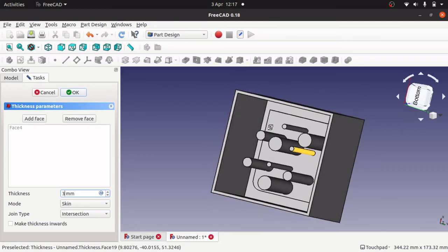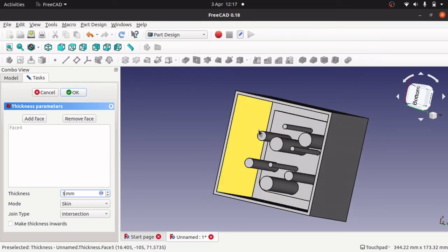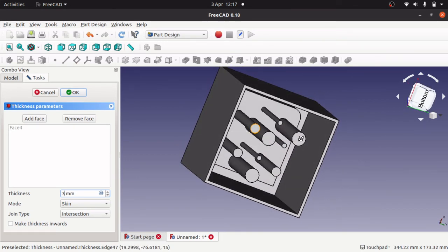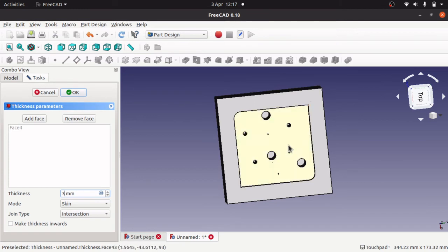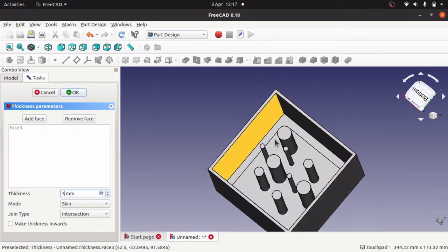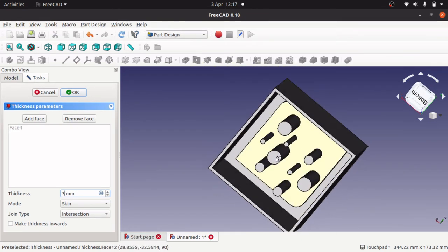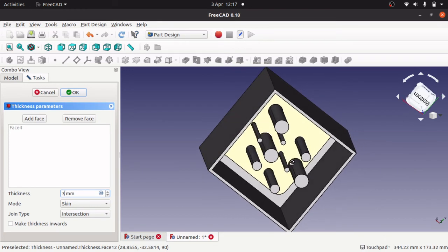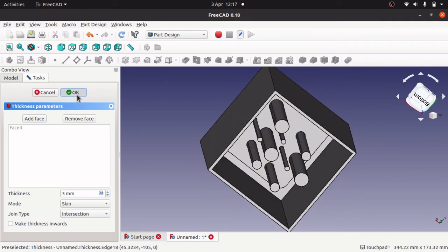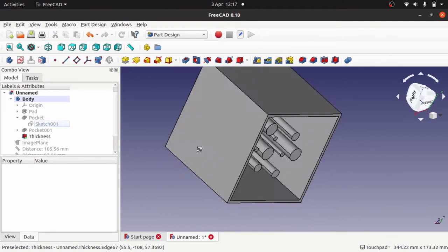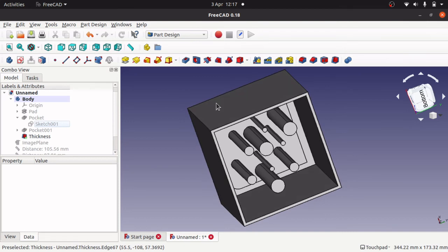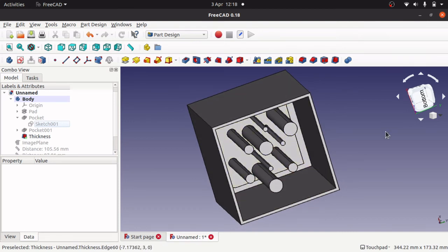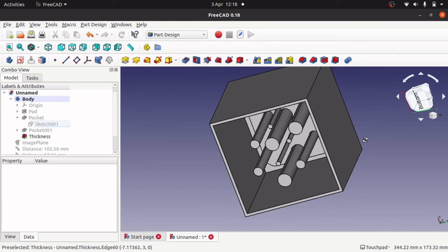So when we fill this with clay or some other material, then we should get the right shape when it comes out. And if you look at the top, we can see that's actually changed the top as well, but we've got the right dimensions for the individual holes that we can actually push into the material. That's okay, and that's basically how you would actually create a mold for something like a B block. Obviously increase the count of these if you so desire, if you wanted more holes in there.